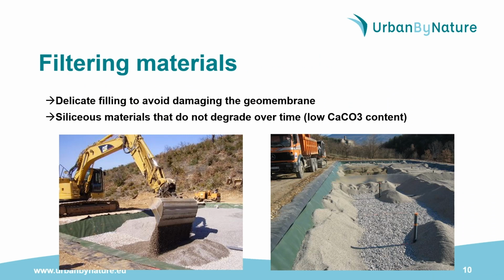Then the different layers of gravel are laid within the filter, taking care not to damage the waterproofing of the basins. The filtering gravel should have a low calcareous content to not degrade over time due to erosion or any acidification of the treated water.